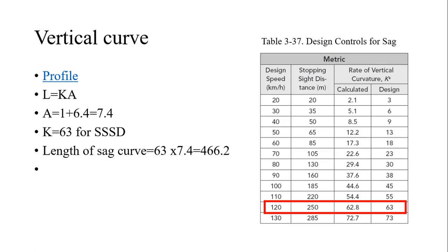As you make it an equal tangent curve, you can always find the point of commencement of the vertical curve, the point of termination of the vertical curve. You can find the lowest point of the curve and all the relevant data that you need for setting out a vertical curve. One thing is, there is one more check.